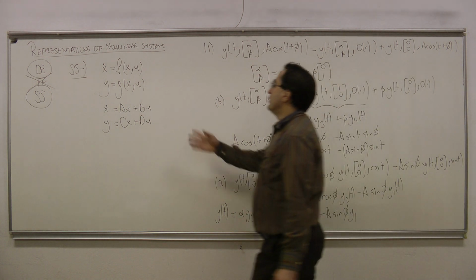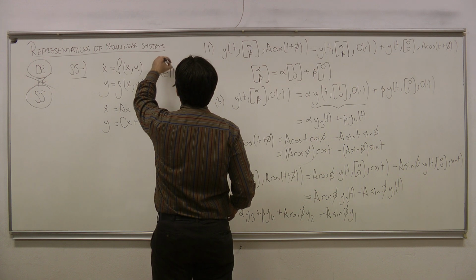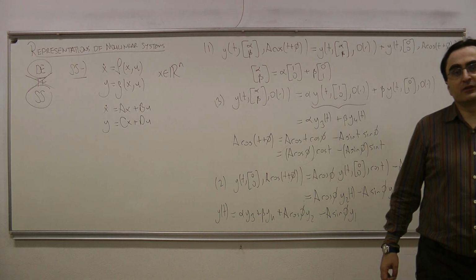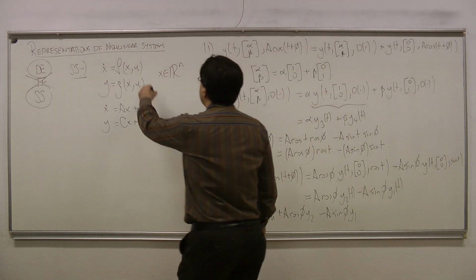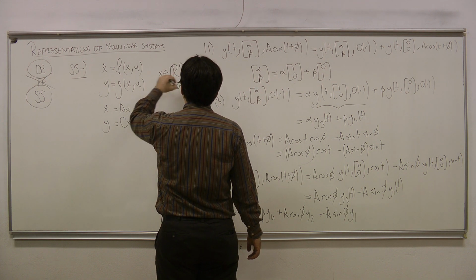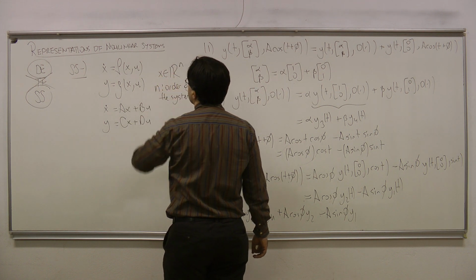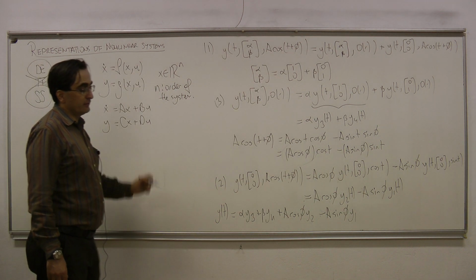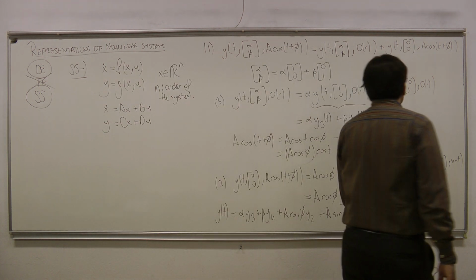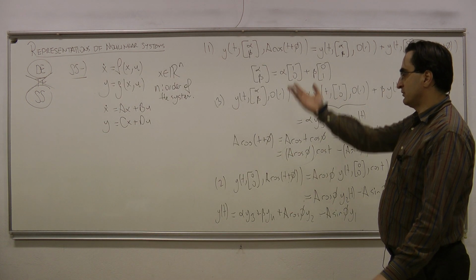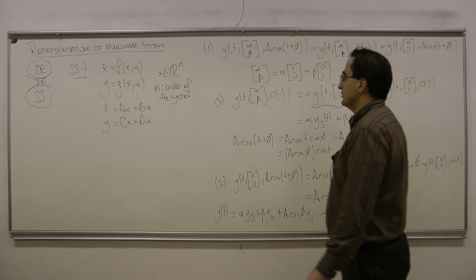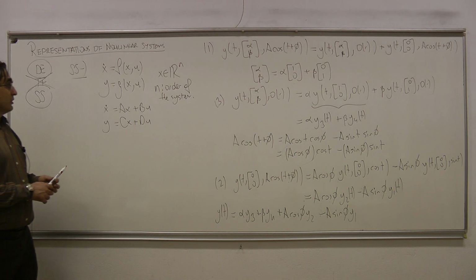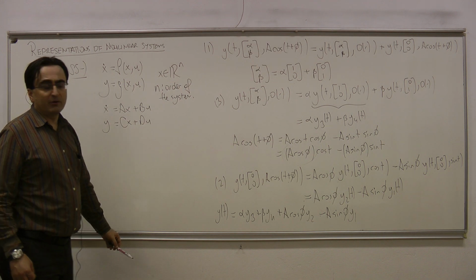And here, we know that the dimension of the state, which is n in general, gives us the order of the system. Okay? So n is the order of the system. It is the same concept for both the linear system and the nonlinear system. And you see that this is a time domain representation. That is a differential equation that I write in time domain. So in this course, we're going to be mostly using this state space representation.